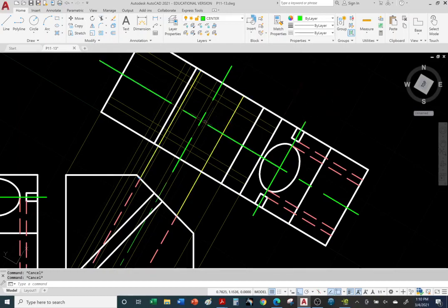Okay, so we know that our circle is going to land between these, inside of these yellow lines. These are the tangent lines, the thick yellow construction lines, and here's our center. And we actually don't need these lines because we can easily define a circle with the center point and a radius. So let's go to the visible layer, draw a circle command, use the circle command, click.